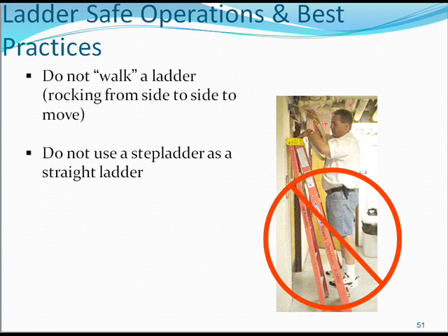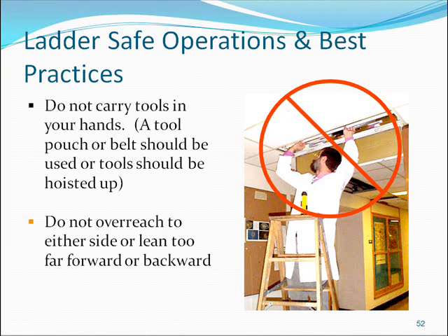Do not use a step ladder as a straight ladder. Do not carry tools in your hands. A tool pouch or a belt should be used, or tools should be hoisted up. Do not overreach to either side or lean too far forward or backwards.